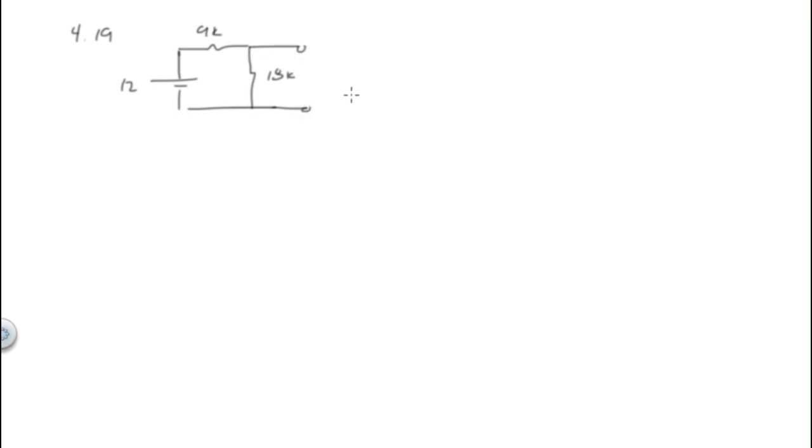All right, so we've Thevenized this, and we get 2/3 of 12, or 8. 18 over 18 plus 9 is 2/3 of that. 18 in parallel with 9 is what? 18 times 9 divided by 27 is what? 6. So we drop to 6K.